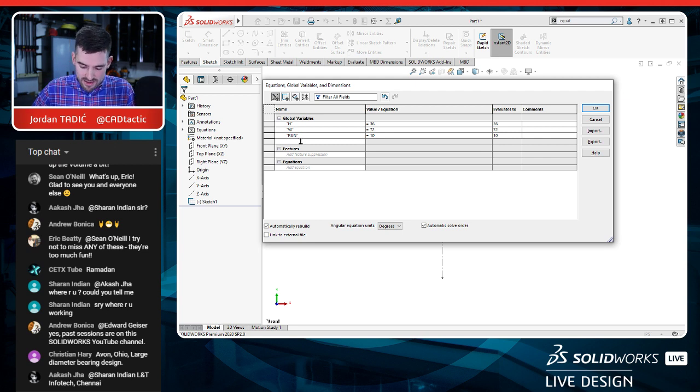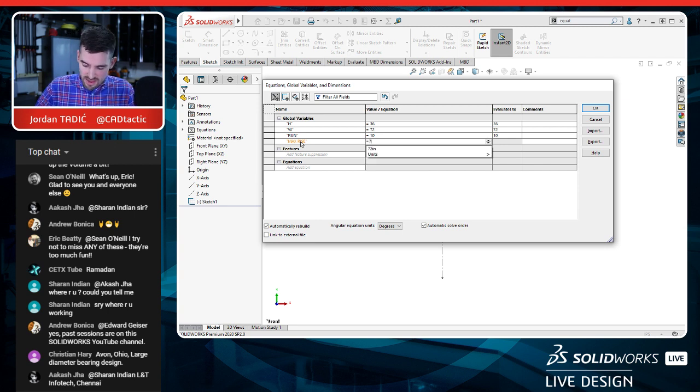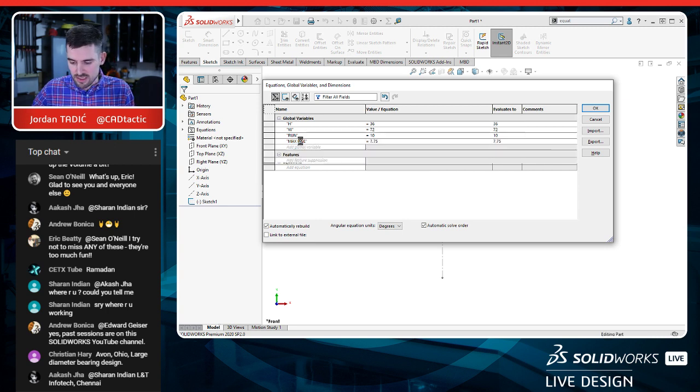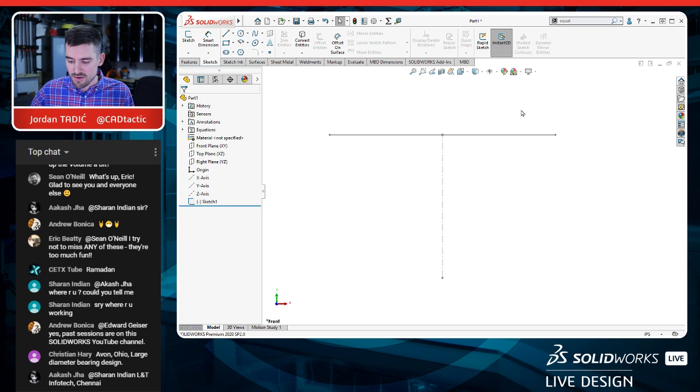And the rise is actually defined by the max rise, the maximum it can be. Because if you get too big, it just gets too hard to climb up that step. And unless you're 6'4" like me, you might struggle. So let's make this 7.75, which is the maximum rise in my municipality, all right? So now we've defined some variables and those input values, and I'm just going to hit OK.